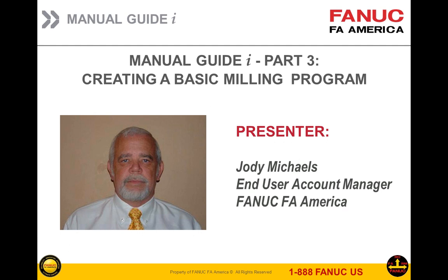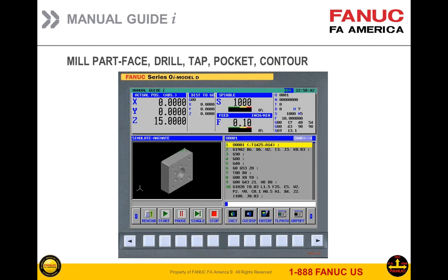And as you said, today we're creating a basic milling program. And what we're going to do today is pretend, and here's the part first. We're going to show the part that we're going to do. We're going to face it. We're going to drill it. We're going to tap it. We're going to pocket. We're going to contour the part. And this shows a representation of what we're going to do.